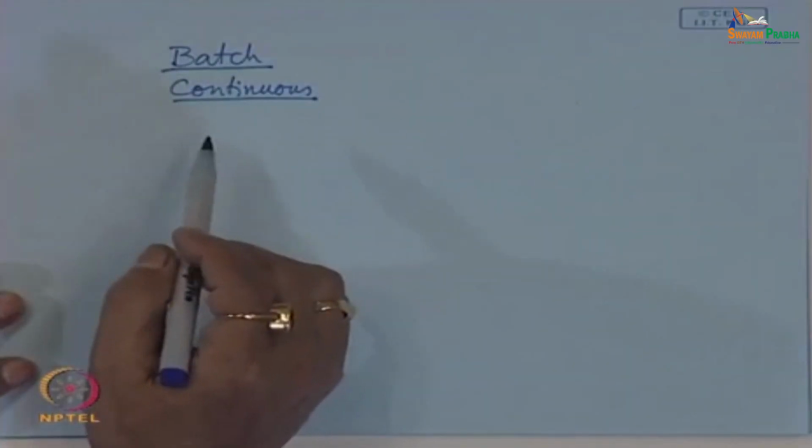After the polymerization is over, that means after a suitable level of conversion, say 60% or 70% conversion, you have to stop the polymerization, remove the mass from the reactor, and then isolate the unreacted monomer and other ingredients present over there to get the polymer. That actually needs more time.